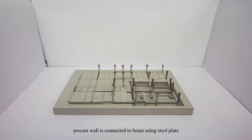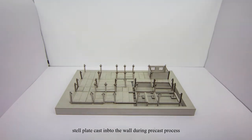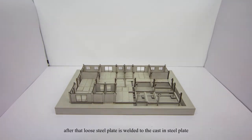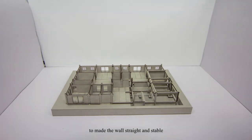Precast wall is connected to beam using steel plate. Steel plate is cast into the wall during the precast process. First, grout is filled at the bottom of the wall. After that, loose fill plate is welded to the cast-in steel plate to make the wall straight and stable.